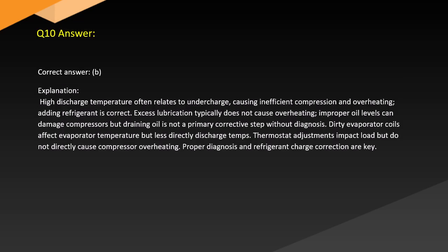Answer. Correct answer: B. Explanation. High discharge temperature often relates to undercharge, causing inefficient compression and overheating. Adding refrigerant is correct. Excess lubrication typically does not cause overheating. Improper oil levels can damage compressors, but draining oil is not a primary corrective step without diagnosis.